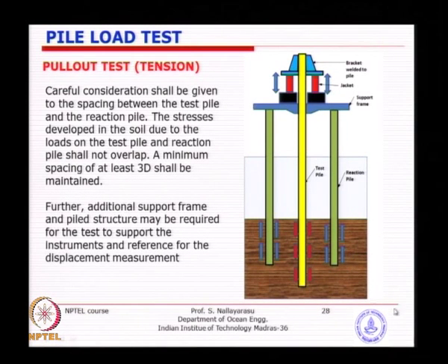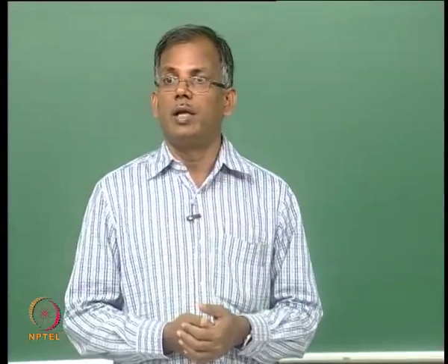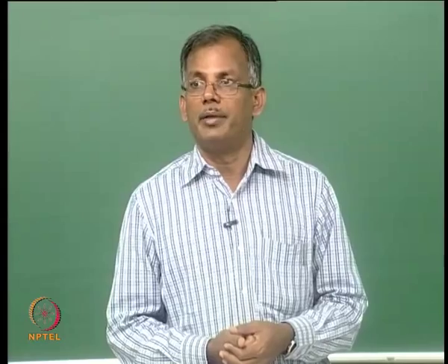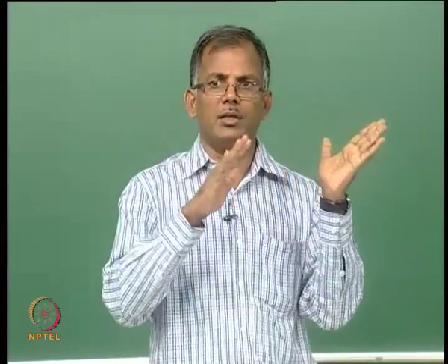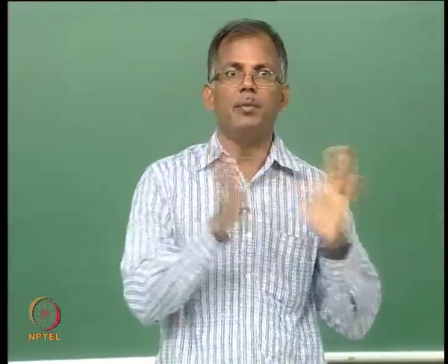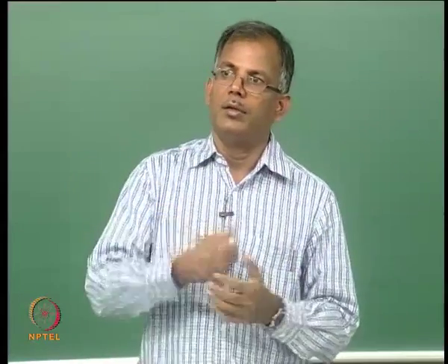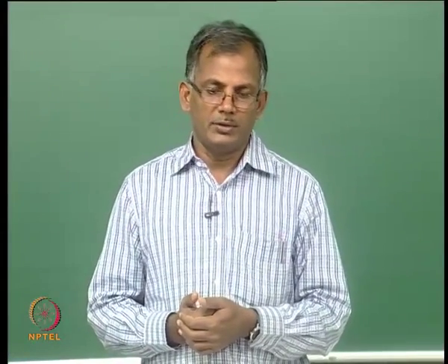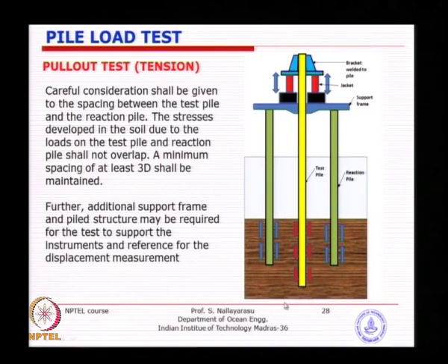In some cases, in coastal structures like berthing structures, we may require a pull out test, because some of the piles are going to have a tension capacity requirement, especially when you build a berthing structure. The front pile will be in tension and the back pile will be in compression when ships are berthing against the berthing structure. So you may require a pull out test instead of a compression test.